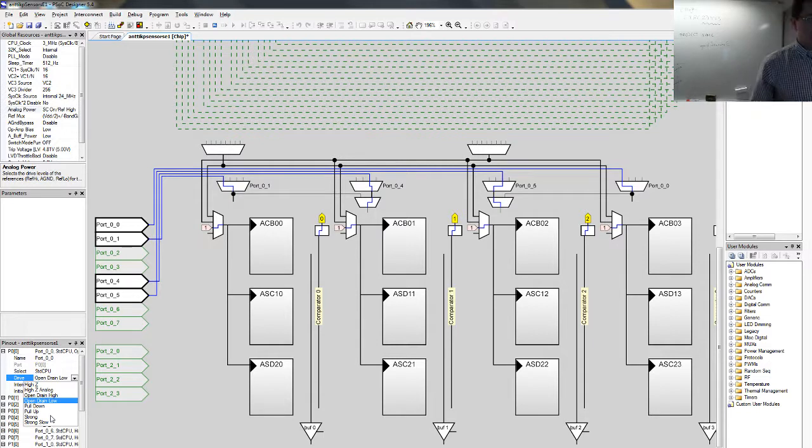Then there are two modes of strong, meaning a totem pole. So there is a transistor on both the high end and the low end. That's the most typical for an output signal. Then it can actually drive anything. Strong slow means that it gives more power, but the rising edge and falling edge are slower. It doesn't generate that many transients. Okay, good.